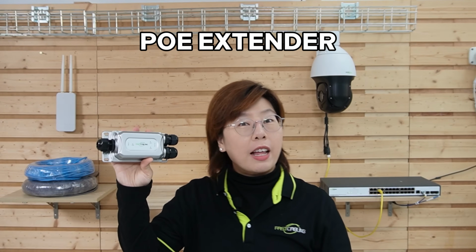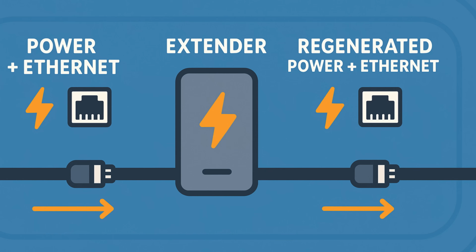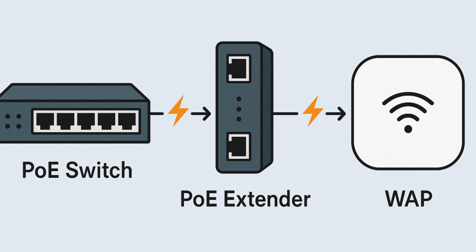And here's where the hero of today's video shows up, the PoE extender. Think of a PoE extender as a pit stop on a long highway. Power and Ethernet travel down the cable, they hit the extender, then the extender regenerates both the voltage and the data signal, and sends them out again. And you don't need an extra power outlet where the extender sits, because it's powered by PoE from the switch side, then passes that along.